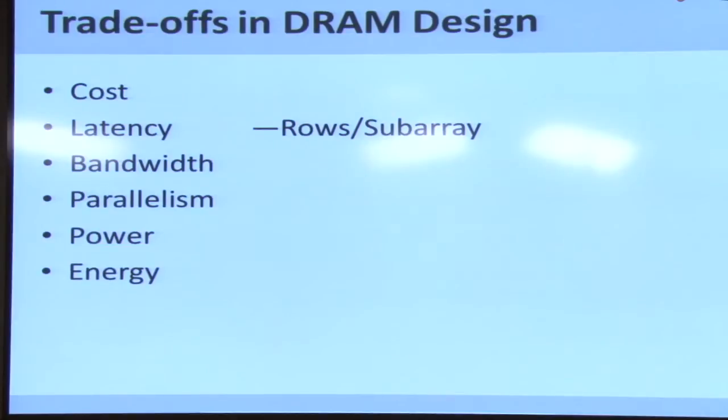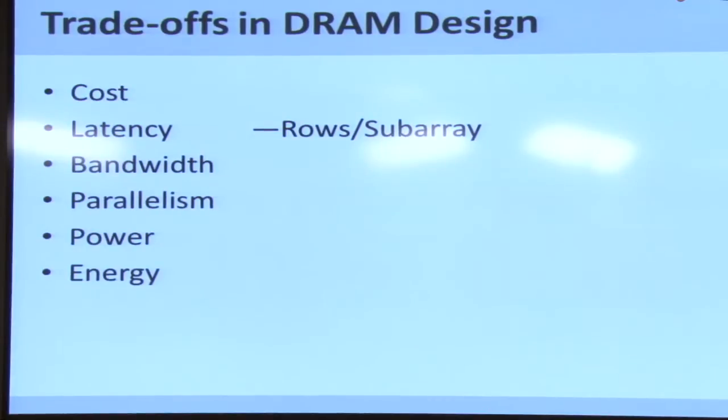So there's a row buffer which has 8 kilobits of data. So my row buffer has more than enough data to send even, let's say, 512 bits, right? Absolutely. But there was another bottleneck at the bottom of the bank, which was the bank I/O logic, which I said in today's systems typically has 64 bits, right? Now it seems like even 64 bits is wide enough. I'm just sending 8 bits. Why would I fetch 64 bits in my bank I/O logic if my data width is only 8 bits?